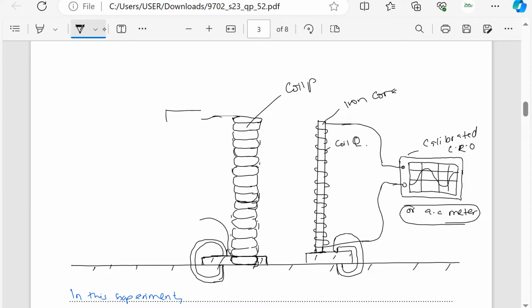I have a resistor. Because I may want to find the PD across this resistor, I'll put a voltmeter across. Then I may want to find R from V over I, so I need an ammeter which is in series.